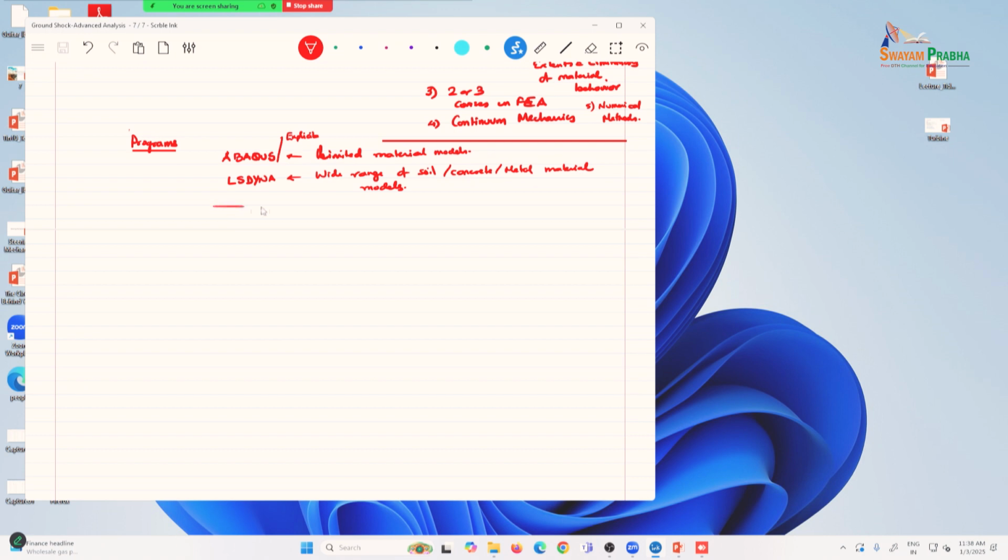So, if you, and there are others, Autodyn. I think one of you was mentioning NISA. I haven't used that myself. I've developed material models for explicit, Abaqus explicit. You can also develop your own material models using what is known as VUMAT or UMAT in Abaqus. Similarly, LS-DYNA also. So, if you don't like any of the materials, there are lots of PhDs that are produced just to develop one material model and run it.